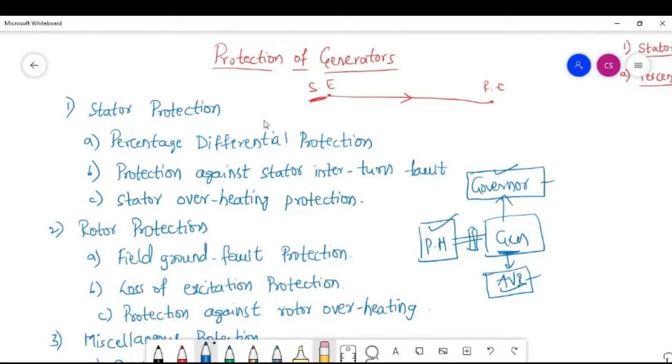We are going to use the same concept that we used for pilot protection, that means we are going to place two CTs. Why the same concept? Because the generator is one unit, so this is also a unit type of protection. If you are providing protection to one unit, we measure at the starting point and also at the ending point. Either you want to measure voltage, current, or power flow, but mainly we depend on current.